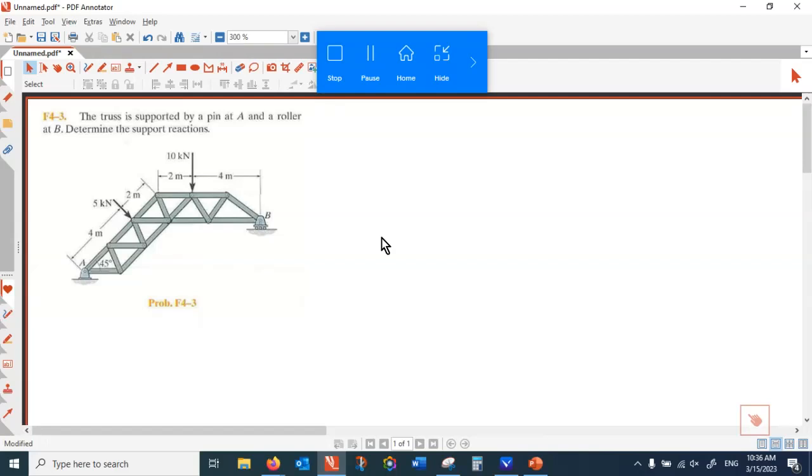When they want to transfer the structure from one point to another, all they have to do is separate the joints, and it becomes a very compact thing to transfer. They can easily erect it, and a truss is a very efficient way of using material. It provides significant structural integrity, uses material minimally, and can take huge loads. So all you have to do is understand how this creature can be studied.